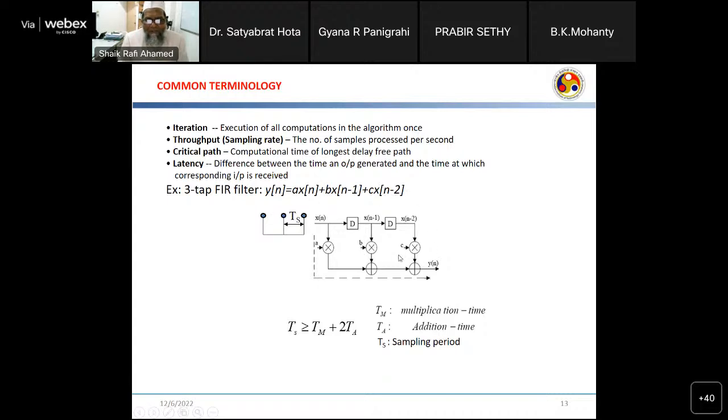This is the relation. This requires 3 multipliers, 2 adders and 2 delay elements. Now we are going to feed the samples because DSP problems are non-terminating type. Like if you take the mobile, we have equalizers and all filters there, so the data will be continuously received on the mobiles. So DSP programs are called non-terminating type because infinite data will come.